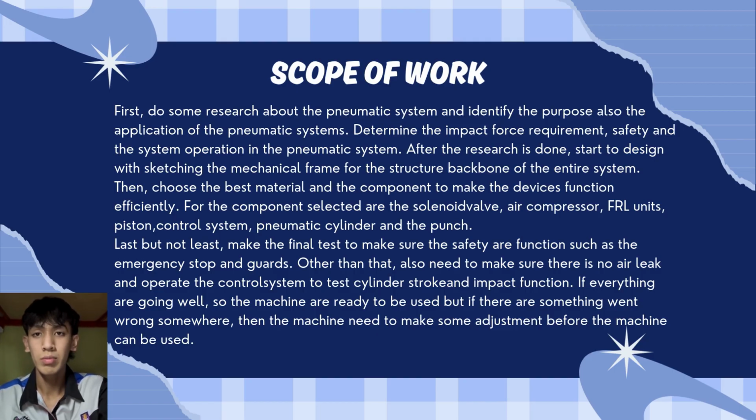Next, suitable components were selected, including the pneumatic cylinder, solenoid valve, FRL unit, air compressor, sensor, and control system. Once all components were selected, fabrication and assembly were carried out. The final stage involved testing the system to ensure proper operation, safety, and absence of air leakage.